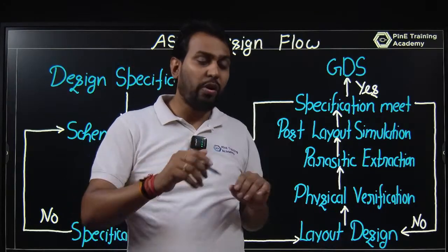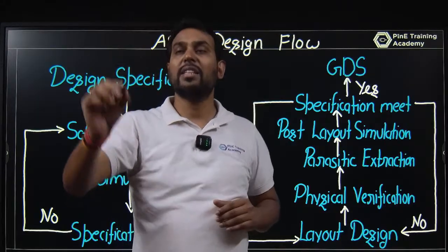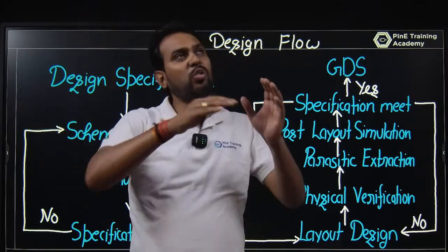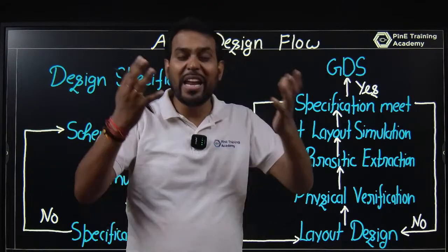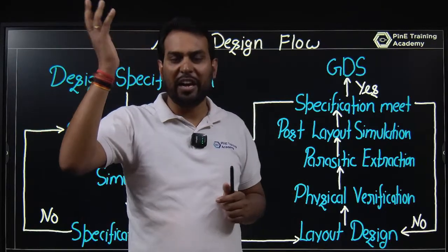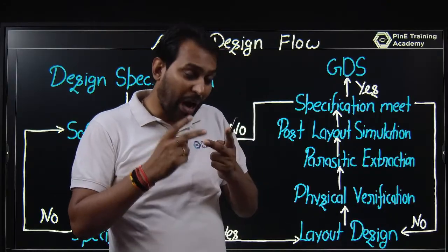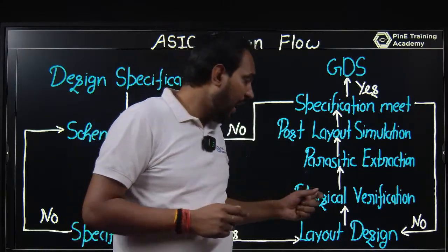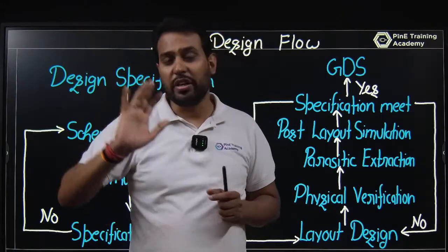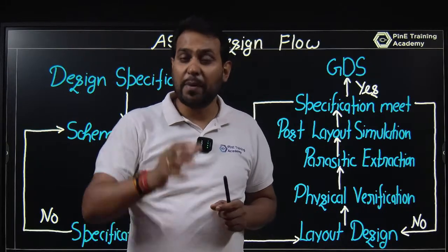Similarly, if a route is possible in a single line and you use a displaced path like this, you are using a different, unnecessary path. Of course it has resistance, and as we discussed in our network class, that is IR drop. So we have power, performance and area: as area increases, it is directly related to cost. Area increases, cost increases. If you increase the metal routing, your delay will increase and performance will decrease.